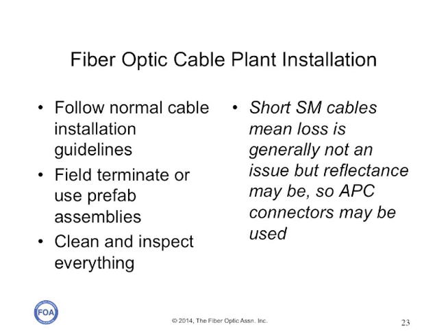Field terminations, particularly on single mode, will typically use spliced-on pigtails or pre-polished splice connectors. If small fiber counts are needed, it's possible to use prefab assemblies where the installation is simple. But as with all prefabs, be careful to inspect and clean every connection. With short single-mode links, loss should not be a problem, but reflectance can cause transmission problems.